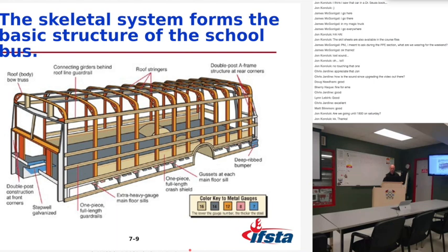Okay, school bus floor and undercarriage. Full-size buses have heavy-duty vinyl or rubber flooring applied over plywood decking and 14-gauge metal flooring panels. Strong. Smaller conversion type has half or 5/8 inch plywood sheets on top of the existing floor.